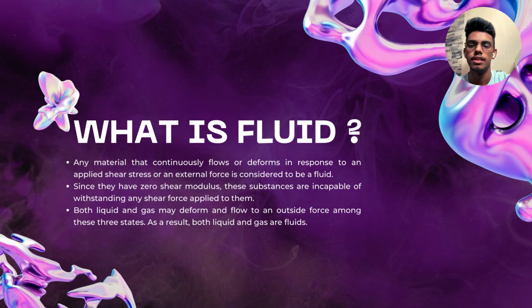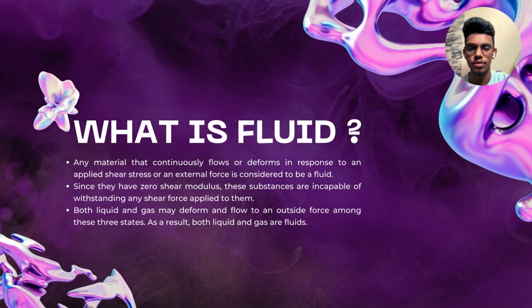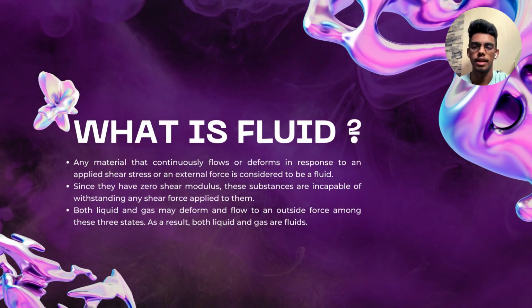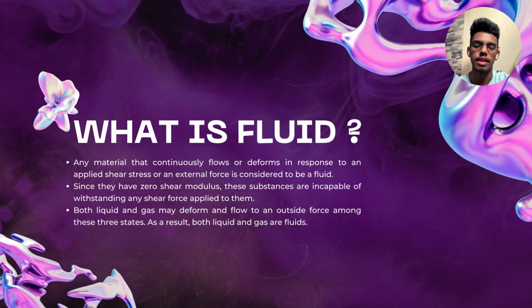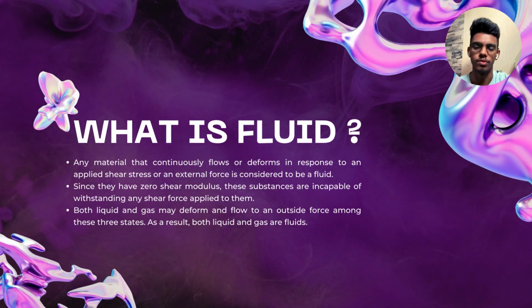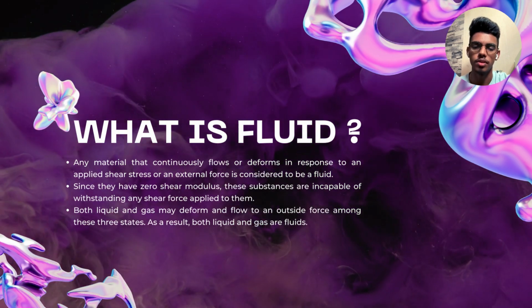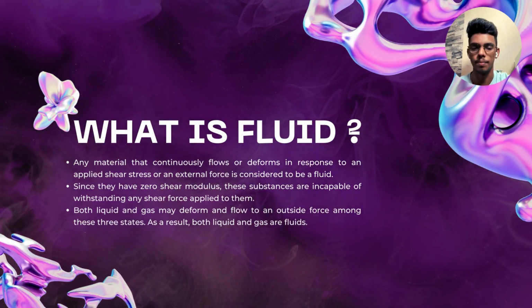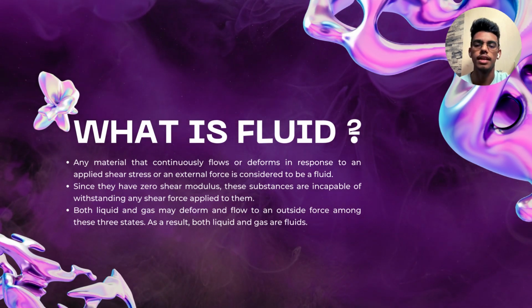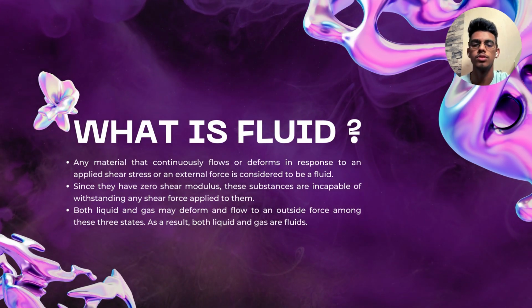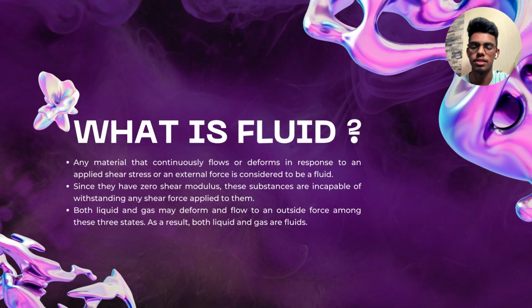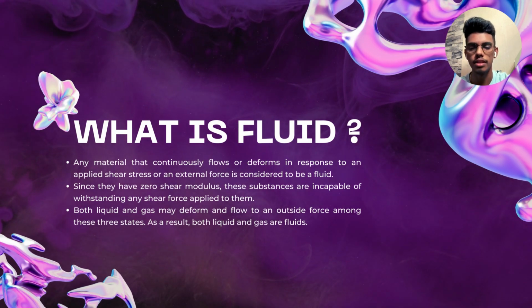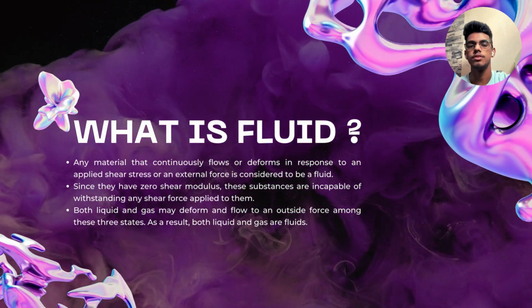So what is fluid? Any material that continuously flows or deforms in response to an applied shear stress or an external force is considered to be a fluid. Since they have zero shear modulus, these substances are incapable of withstanding any shear force applied to them. Both liquid and gas may deform and flow to an outside force among these three states. As a result, both liquid and gas are considered to be fluids.